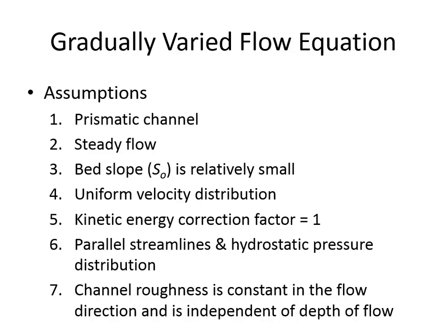The way they reconcile that assumption with the reality that natural channels usually are pretty irregular is they break it up into sections that are quasi-prismatic. If you break it up into pieces, then this is basically a rectangle and so is that, even though taken as a whole, the channel is non-prismatic. Steady flow means that flow conditions are constant over time. Again, that the flow rate is not increasing or decreasing as a function of time.